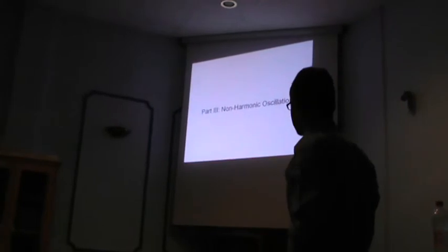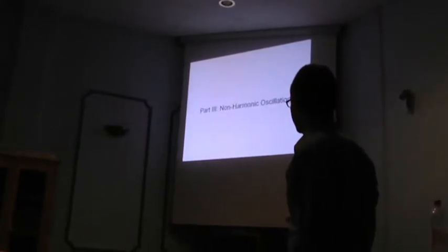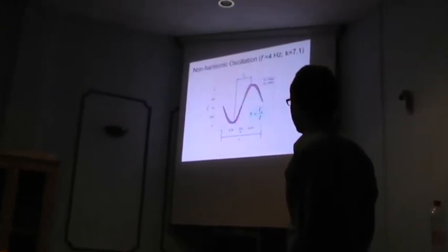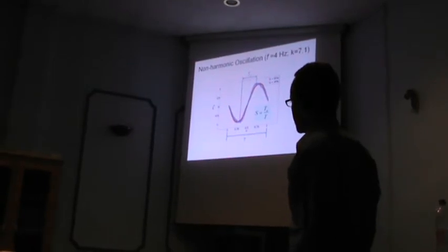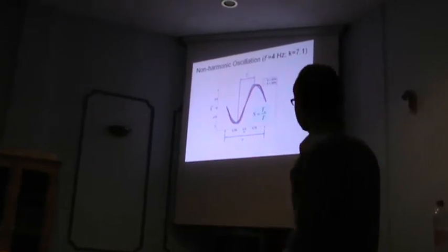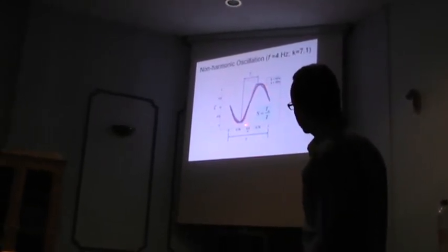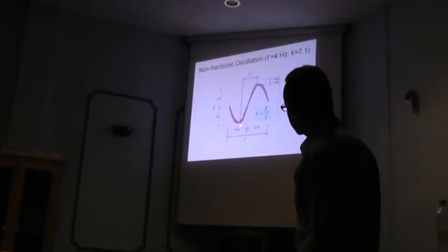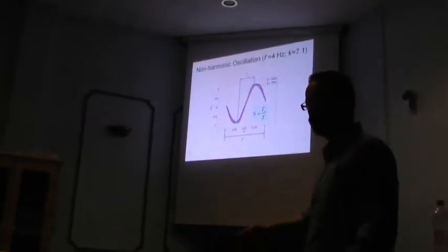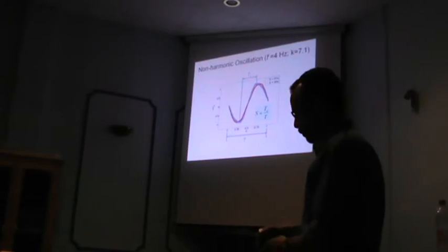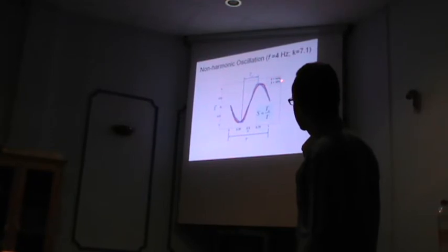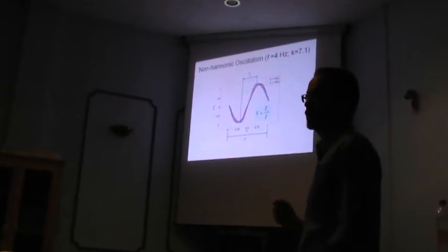In the next three slides, I will just very quickly demonstrate that the model also works for non-harmonic oscillation. In this case, this is the actual angle of the airfoil. The red one is just sinusoidal, going up and down between the two angles. For this blue line, we actually shorten the pitch-up time, so the airfoil is going up faster than it's coming down. The time of the pitch up, as a fraction of the cycle, instead of being 50% for the symmetric oscillation, becomes 38%.